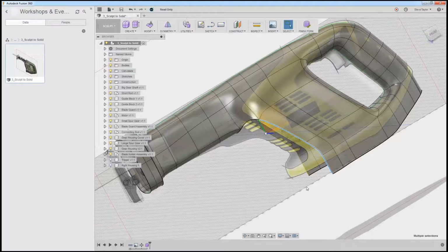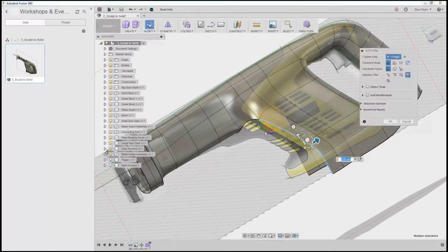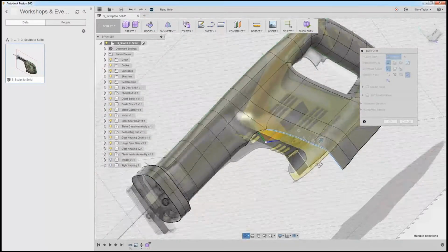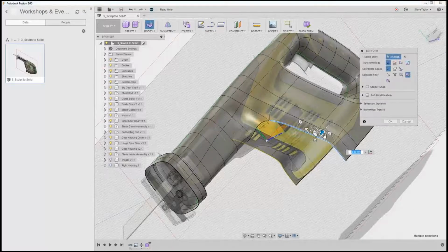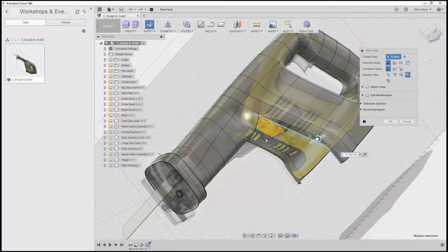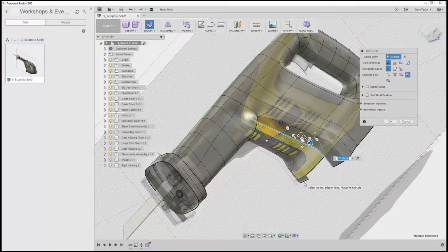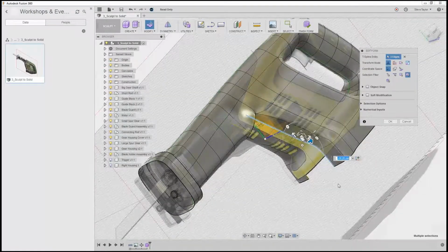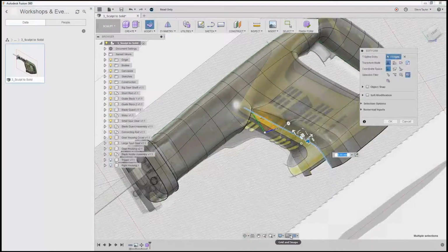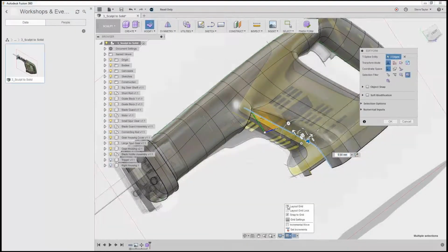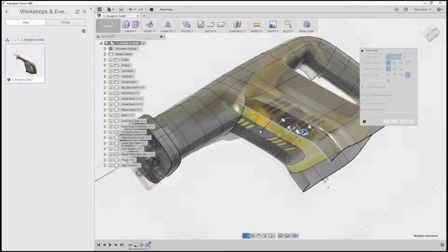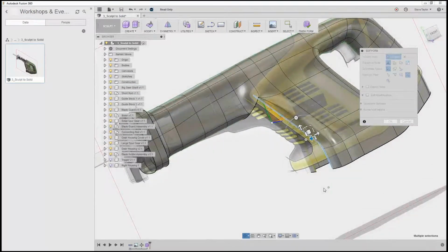Then using modify, using the Alt key and the arrow, what I'm going to do is just bring in here, Alt in, and start closing it off in that direction there. So I've now started to grip and bring in. I'm just going to turn my grid off there. Maybe I'll see it a little bit better there. So you can see I've started to bring that in.